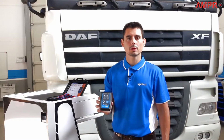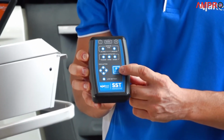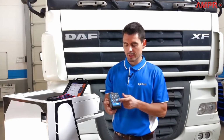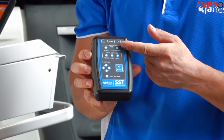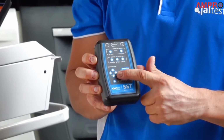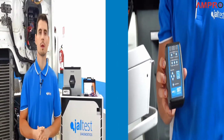In the electronic device we can find diverse inputs for the electrical connections, one main switch or button for turning on, turning off, changing and confirming the mode, and several LEDs that will indicate the sort of sensor we are checking, active or passive, different errors that can be detected if any, and another LED which indicates the status of the signal. Finally, another LED will indicate when the battery is low.